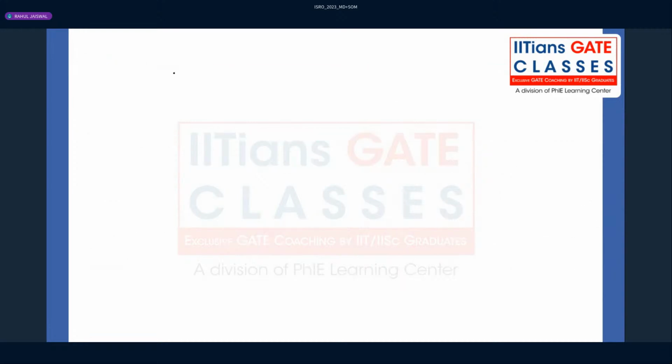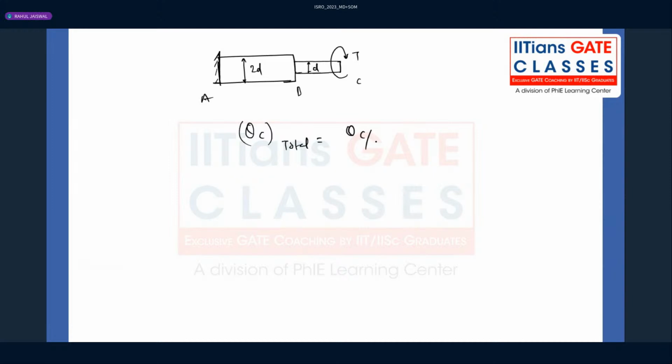So they are saying that if you load the material like this, we are applying the twisting moment T. Here the diameter is 2D, and here we have the diameter D. Let the points be A, B, C. They are saying theta C total, that is theta C with respect to A. We can write theta C with respect to B plus theta B with respect to A, that is equal to theta BC plus theta AB.